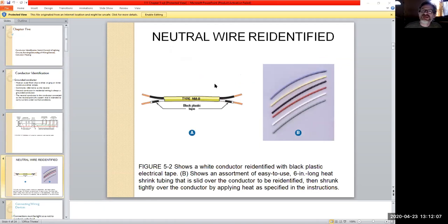And this is the opposite side here. In the Romex, typically it's a very standard 3-wire deal, right? You have a black, a white, and a ground. But in cases where you have to use the white wire as like a line load of some sort, if you're doing lights with switches and that kind of thing, you have to identify it.